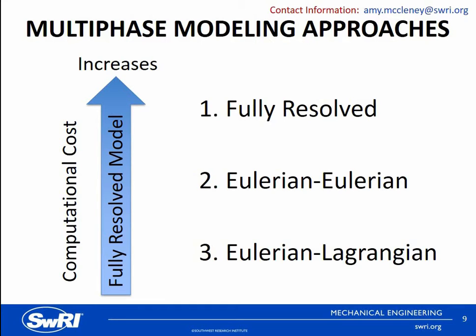In this approach, the most prevalent fluid phase is considered continuous and solved using the time-averaged Navier-Stokes equations. The dispersed phase is simulated as droplets or particles tracked through the flow field based on Newton's second law. A large number of particles are generally required for the sake of accuracy, and the Eulerian-Lagrangian method is normally only recommended when the discrete phase represents 12% or less of the total volume fraction of the mixture. So if you have a secondary phase that is above 12%, this model is not the best approach for solving that multi-phase problem.